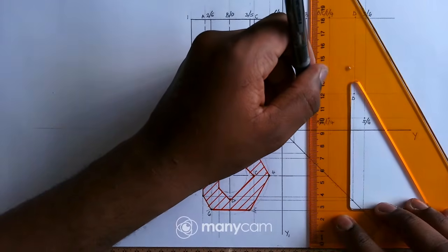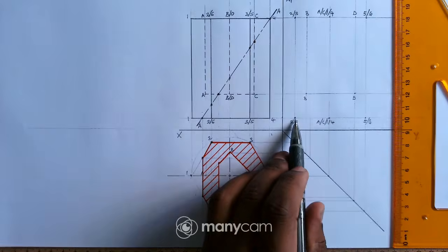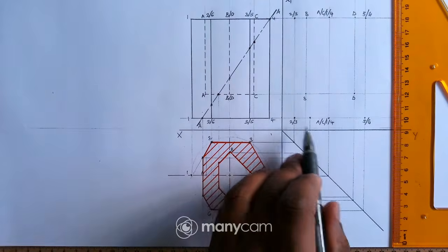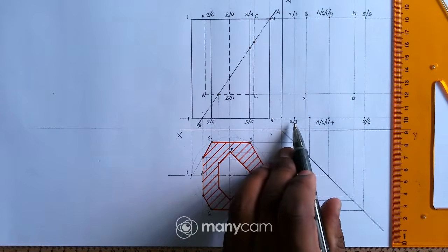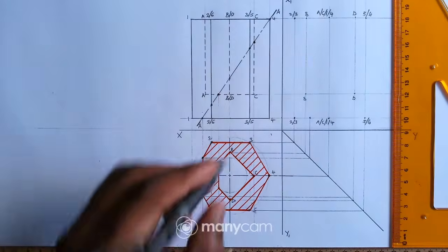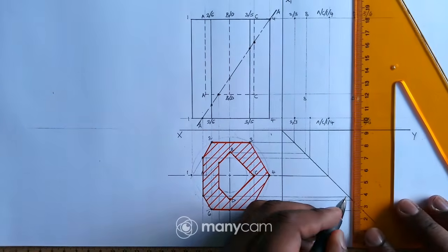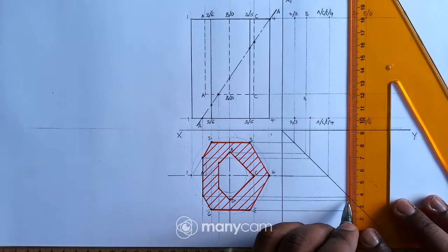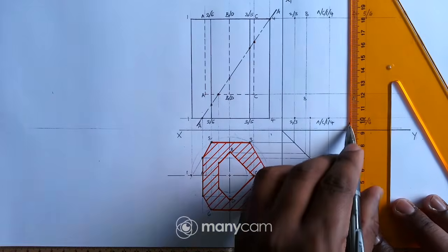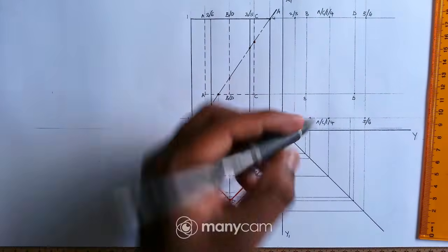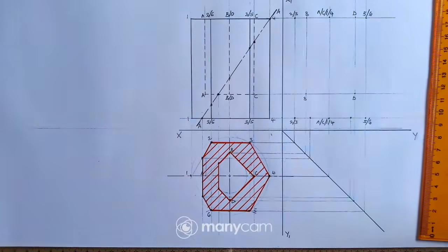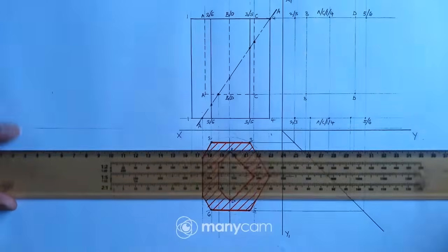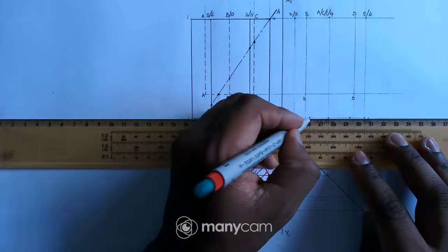So line 1-2 is there. Obviously that line is on the base, so I will only focus on the base. I have the point there, and for this one, this point is on line 1-6, so I can just project this to line 1-6. So 1-6 is right there. That means I have a point there, and then I can just connect these 2 points. So our cut surface will start right here.